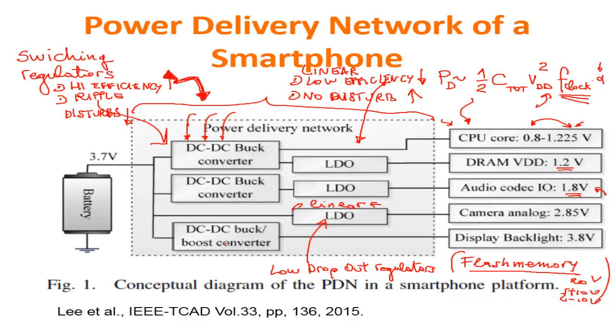So this situation with the many converters and many LDOs is on the main board of the smartphone, but the trend now is to replicate the same system within the chip with different DC-DC converters and different LDOs that provide the supply voltage to different blocks in parallel. So it is something which is occurring in a fractal way.